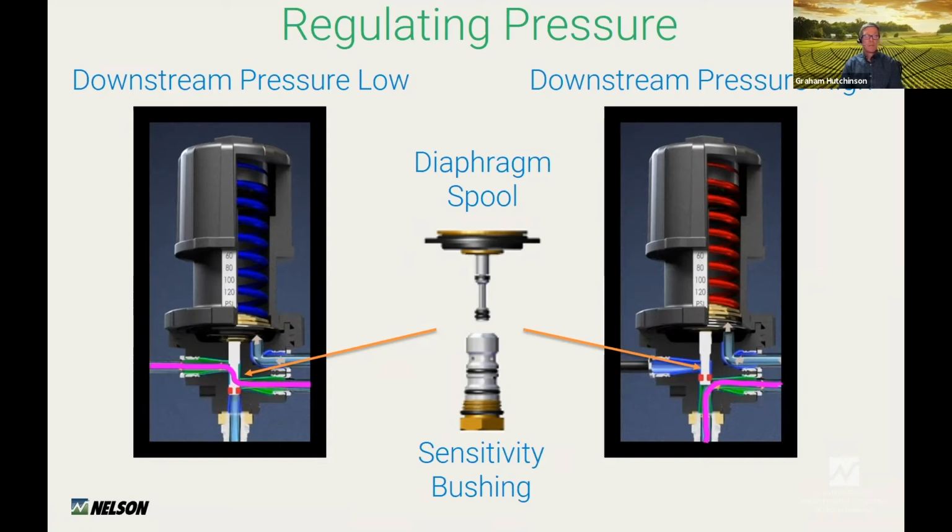The other things that come into play are that the materials are high quality materials. The surface finish on those materials is of a very high quality, which eliminates friction. Some competitors will put oil lubricants into this spool assembly. And while that may help when the pilot is new, that lubricant often gets washed away, or if not, it is contaminated by sediment, and then the accuracy of the pilot really goes downhill from then on.